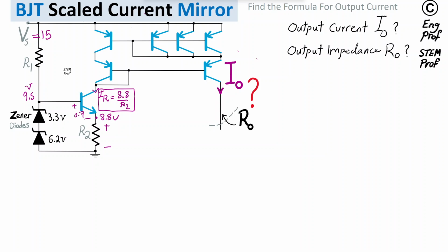As I said, let's make the assumption, for example, Vs is 15 volt. So we have good margin versus 9.5 volt. We can select, for instance, R1 to be 500 ohm as an example. Let's say we select R1 to be 500 ohm. And with that, given the 15 to 9.5, so basically a 5.5 volt drop across R1, then with the 500 ohm selected, as a result we get about 11 milliamp current that is going as the bias current toward the Zener diodes.